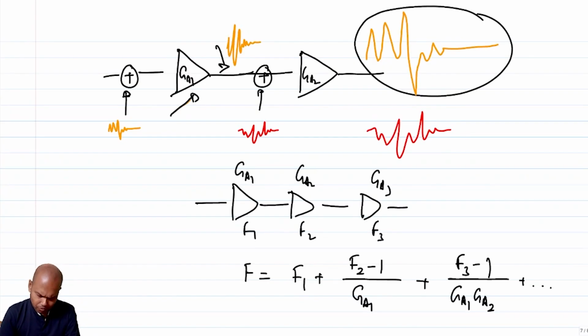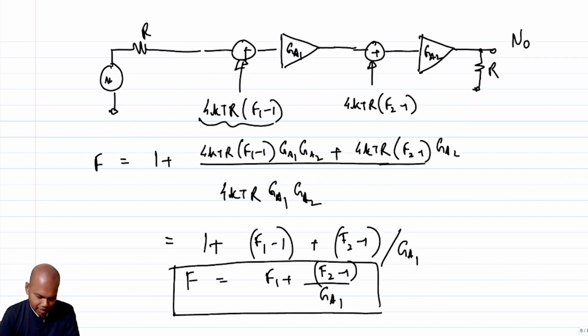So before we end the discussion on noise figure of cascaded systems, you saw that I have done this analysis by assuming all the interfaces are matched. But in practice, when things come inside the chip, they are hardly ever matched, because matching is required only if the length of the wire through which the signal has to travel is of the order of the wavelength. Inside the chip, that is not necessarily true. So you can have a lumped element model and you don't have to do matching.